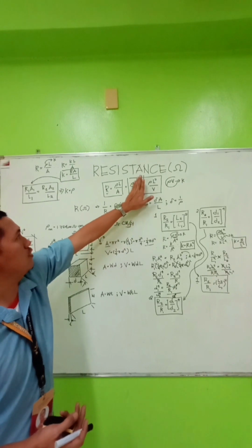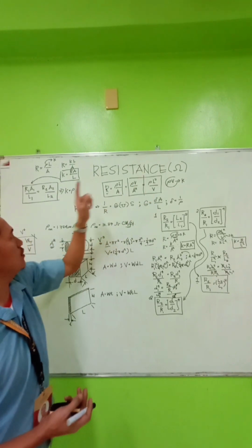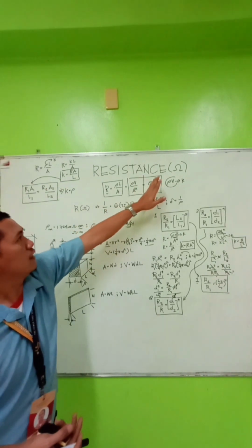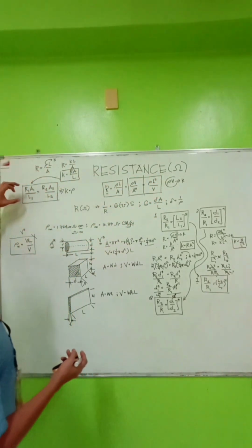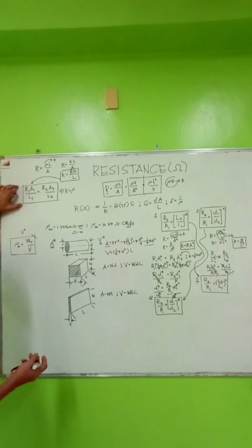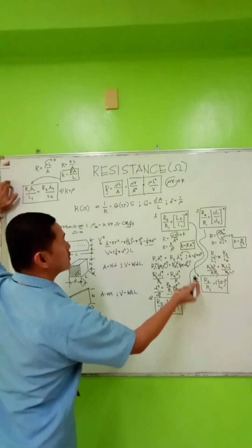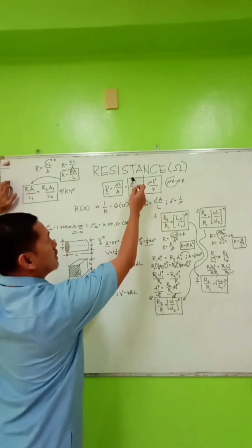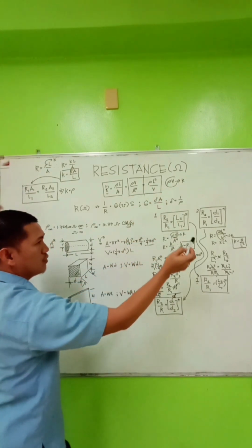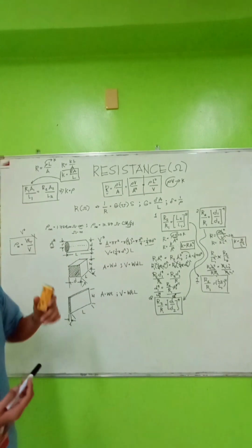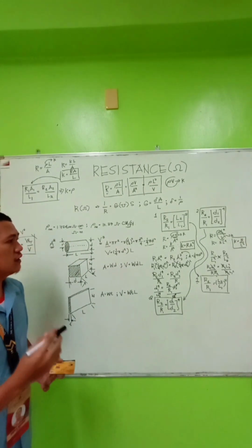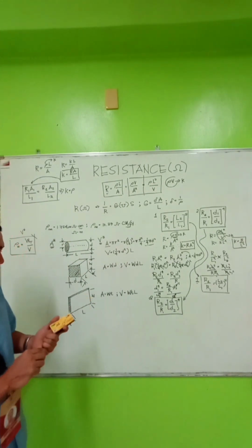If you made your resistivity constant, you can do it like this. And for this third formula, if your resistivity is constant, you can do this process. Or in the drawing process, where both the resistivity and the volume are constant, you can determine these two formulas. Okay, so that is our electrical resistance in ohm. What are the other things that you need to remember?